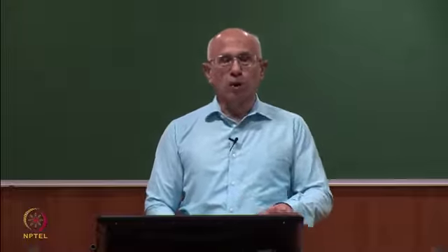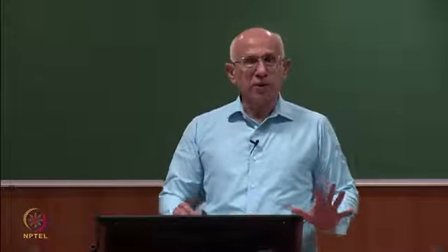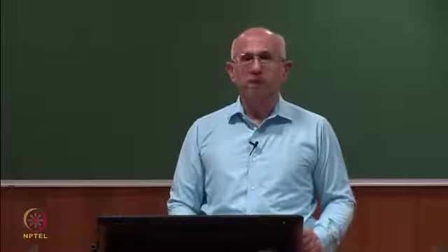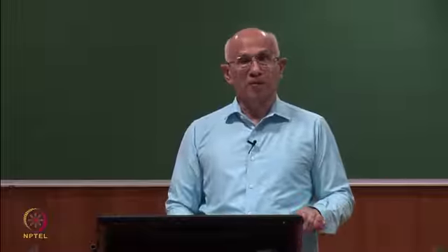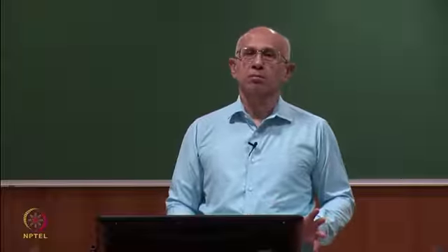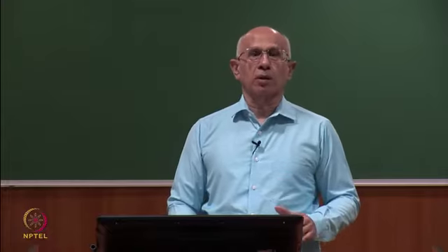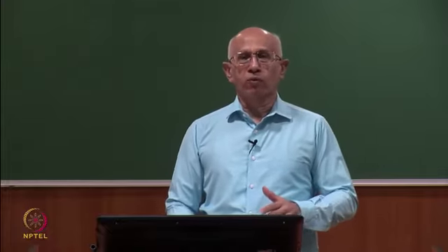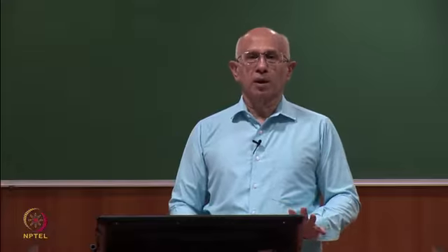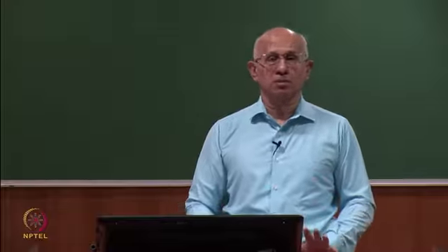So, we will do more of these exercises as we go along in this course, that in all these dimensioning we have to make sure that we have given adequate, appropriate information, and there should be no contradiction in the information. That is what one needs to do when checking a drawing: if the drawing falls short on any of those, we should not proceed with it, go back, correct it, complete it, and then only we work with it.